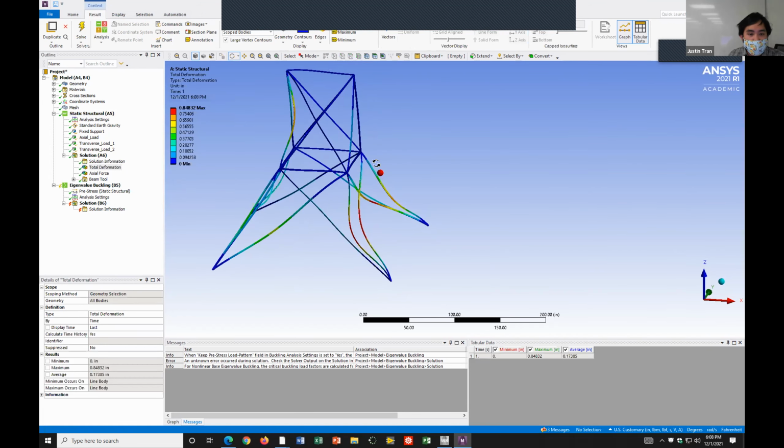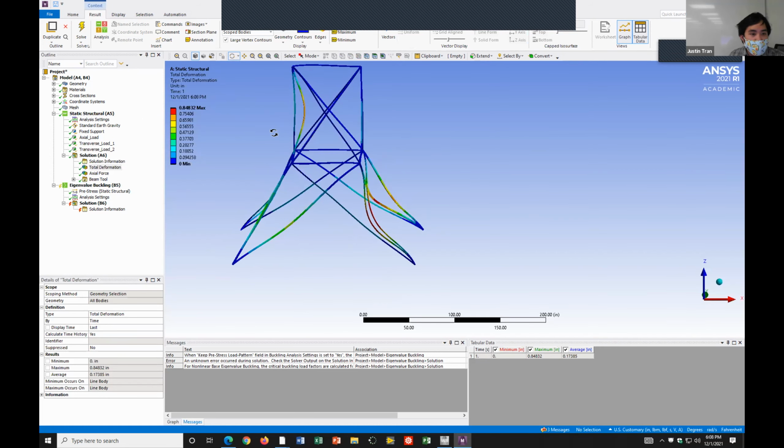Okay. And so I think for this one, buckling did indeed occur, because I increased my load by a factor of 72%, but then my deformation increased by like 2.5 times from before, right? Because remember, the old deformation for this used to be 0.39, but now the deformation is 0.85, that's more than 2 times that. And so when the amount that your deformation grows exceeds the amount that your load grows, that's a good indication that buckling has occurred.